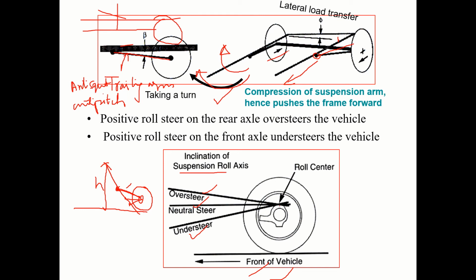So suspension, that is the reason you see here, this suspension roll axis we are talking about here. Another very important thing. So that is the reason roll center at the rear is kept high compared to the front, so that when we can join these two, this will be in this form, it will make the vehicle understeer again. Okay, lateral roll. So these are important.